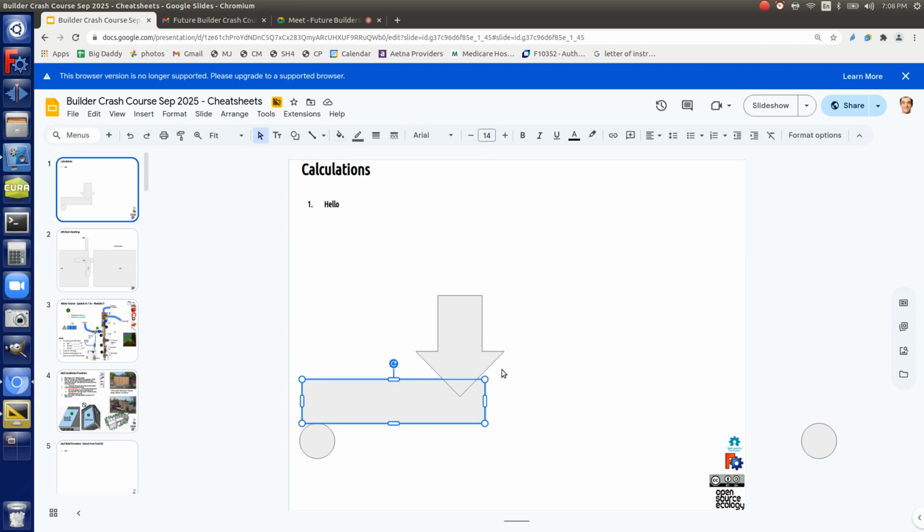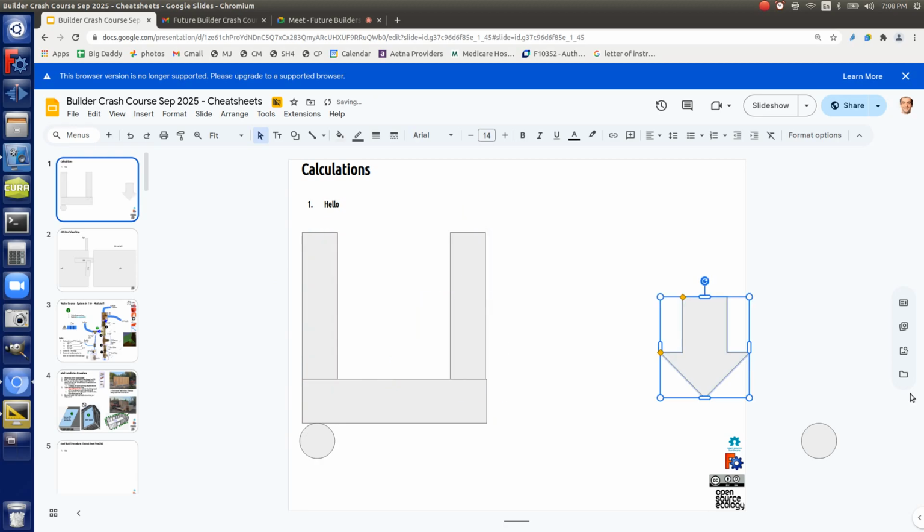Okay, so say we're doing this for steel. You've got deflection calculators online. We do that all the time here, that's why I'm bringing it up. If you have, for example, a 4x4 tubing frame on a tractor, a box frame, say you want to design a skid steer. Well, industry standard is 5, like that skid steer only carries about 3,000 pounds max. I'd like to actually design ours for 5 or 7, same size. Say we want to carry 7,000 pounds.